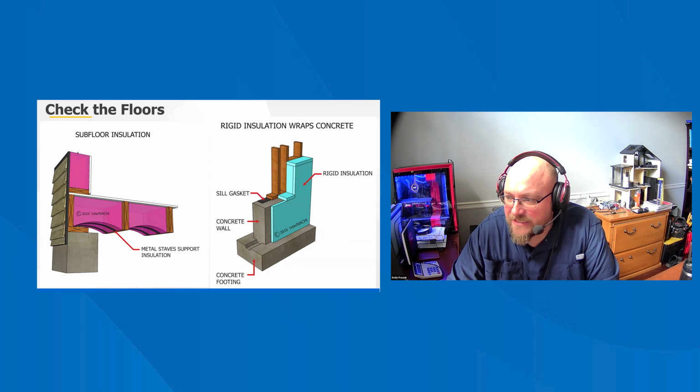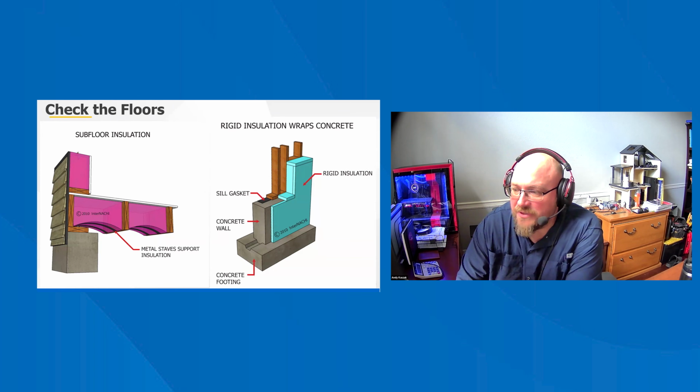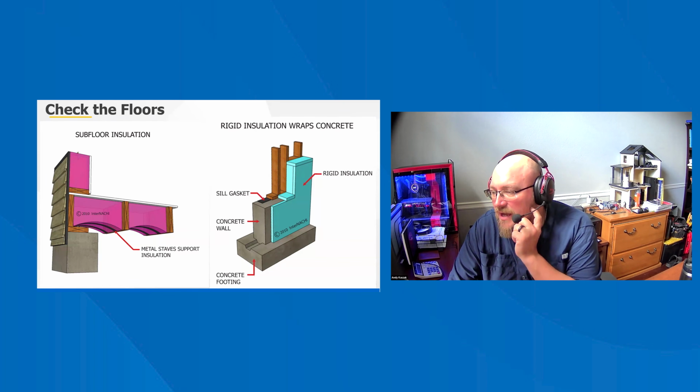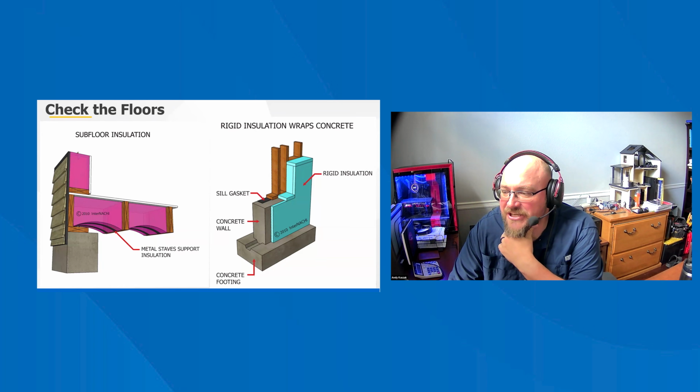In a non-ventilated crawl space, you may see fiberglass blanket insulation installed on the perimeter walls attached to furring strips. You may also see insulation fastened to the sill plate and draped down the perimeter wall of the crawl space. The insulation may continue over the crawl space floor for a couple of feet on top of the required ground vapor diffusion retarder. Foam insulation installed on the walls of a non-ventilated crawl space may be bonded to the wall using adhesive. If any insulation is exposed, consider checking the local fire codes and the flame spreading ratings of the insulation.